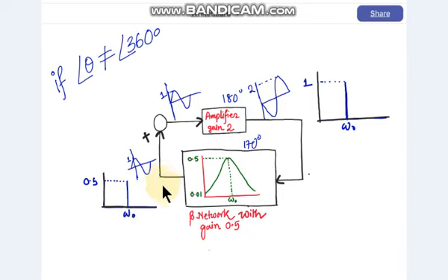And the important point is that this is happening at a frequency omega naught. So this minus 10 degree phase shifted output of the beta network will go to the input of the amplifier block. But initially the input of the amplifier block has no phase. It was a pure sine wave. So because of this minus 10 degree or 350 degree phase change, there will be a loss of synchronization.